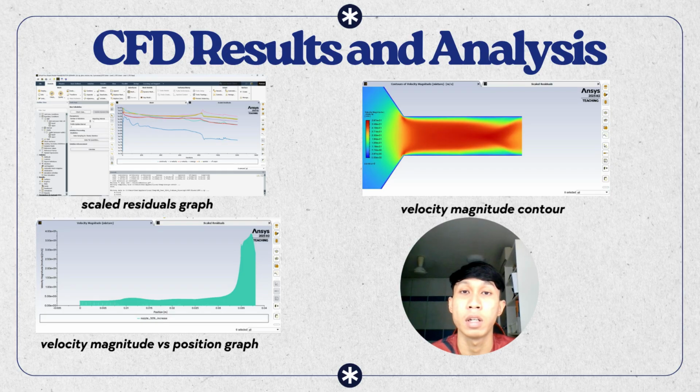Explain about the result in this project. First is the residual convergence graph. This graph shows the scaled residuals for the CFD simulation after changing the nozzle diameter. The residuals represent the numerical errors of the governing equations, including continuity, velocity, energy, turbulence, and vapor volume fraction.